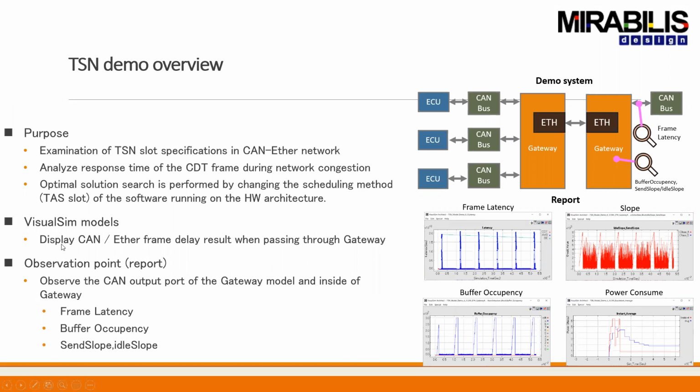So one of the things we can do here is start with looking at the latency. What is the latency for each of the scenarios? And then figure out where the bottleneck is happening. So we want to compare the buffering, the latency, and the credit information to come up with how we can modify each one of those in such a way that we don't see these spikes. The spikes get completely eliminated and we don't see the buffer occupancy.